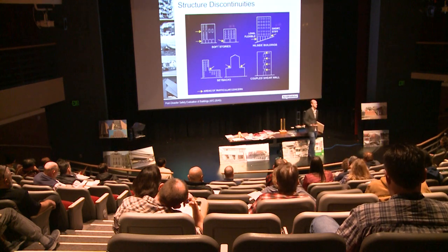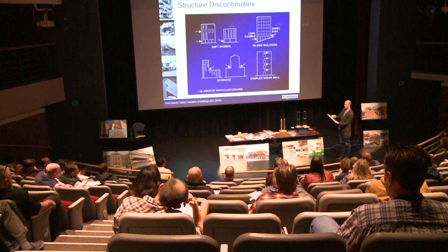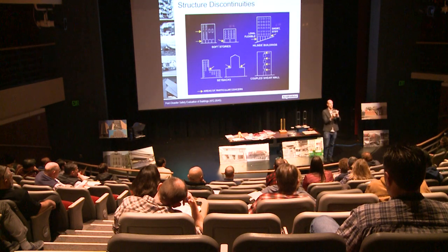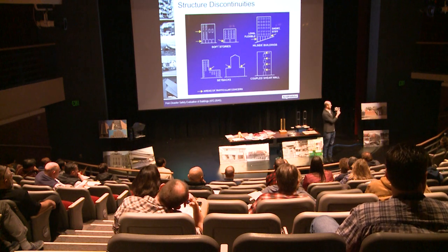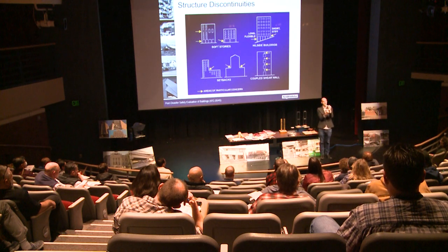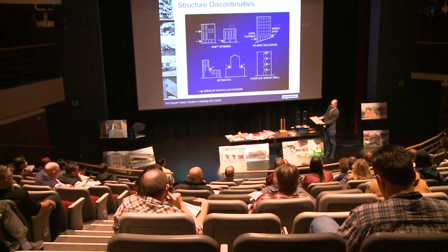The way we think about buildings as structural engineers is a series of springs in parallel and in sequence. And so it's very simplistic, actually even more simplistic spring model here. We have our stiff and our flexible spring. Your right is the stiff and your left is the flexible. So if I pull these, which one's going to take more than its fair share of load? The stiffer, the right one. And then here's a depiction of that in a plan view sense. So I lost my puller thing, but this is a much stiffer spring than this.